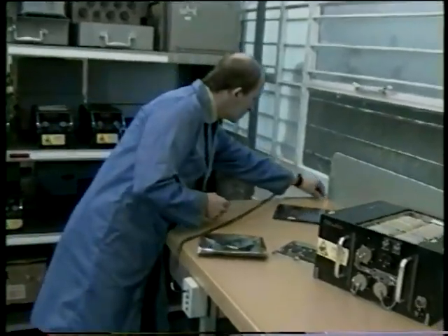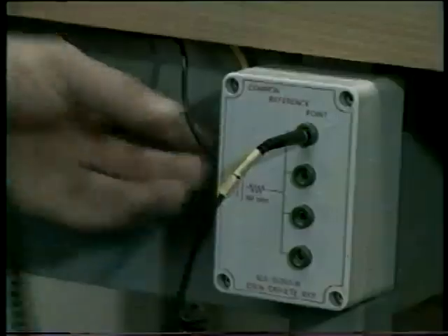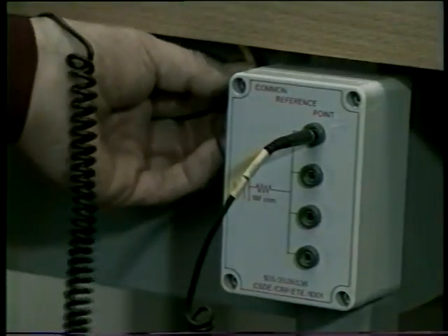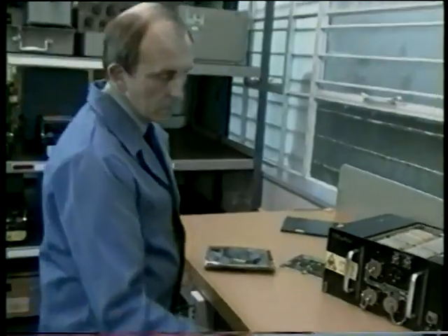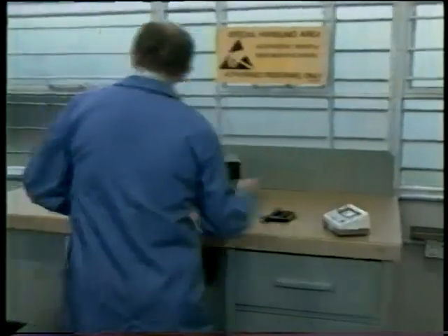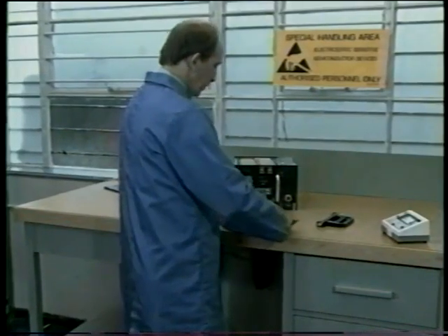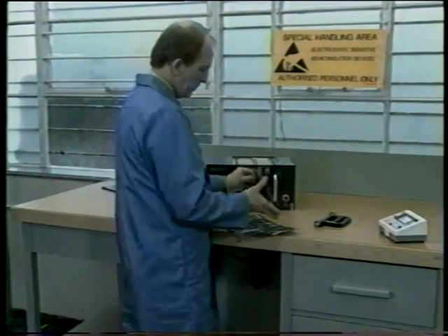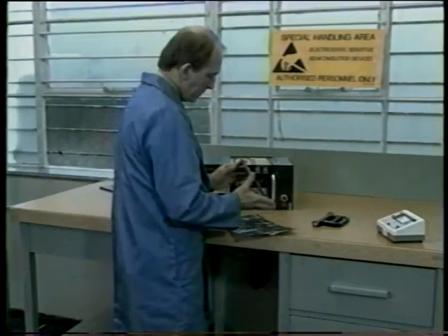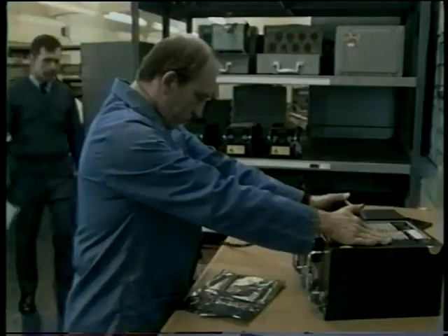Yes. Make sure that the bench mat is connected to the common reference point and that the mat and all connecting leads look in good condition. With the Type 1 SHA, you need to test that the RCD is operating correctly. Monthly detailed inspections will check that all of the equipment is actually okay, and should any surfaces need cleaning, use only those materials approved for the job. Don't forget to check for extraneous plastics and other possible sources of static charge, and also to ensure that personnel who are not earthed do not approach the bench, regardless of their rank.